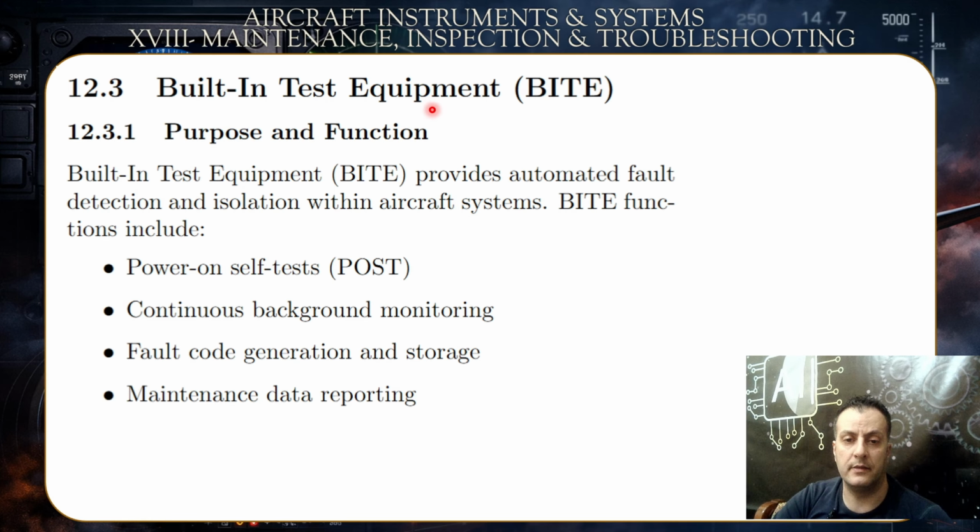BITE, or built-in test equipment. Purpose and function. Built-in test equipment, or BITE, provides automated fault detection and isolation within the aircraft systems. So automated detection of faults and also isolating these faults while recommending potential fixes, or potential solutions for the problem.